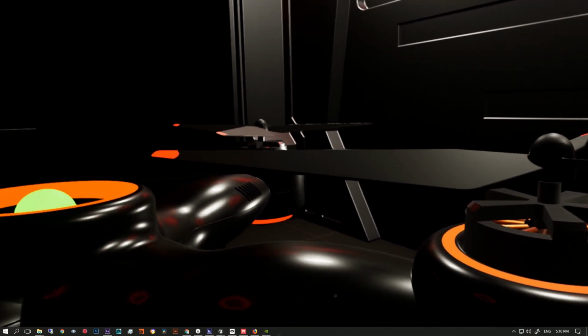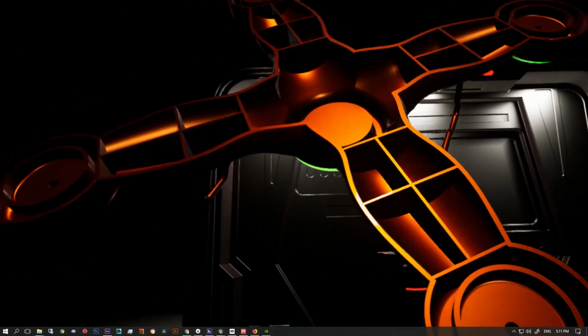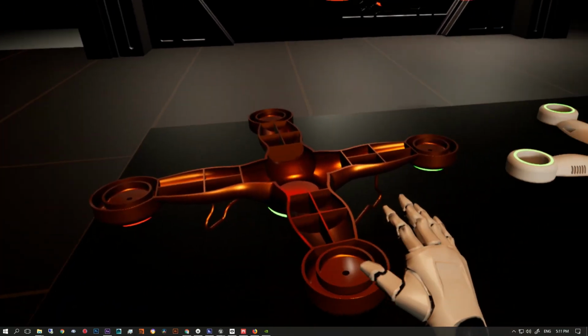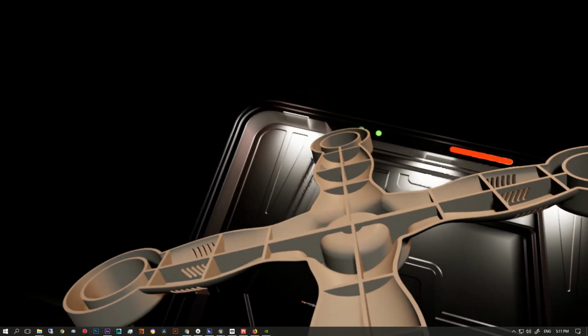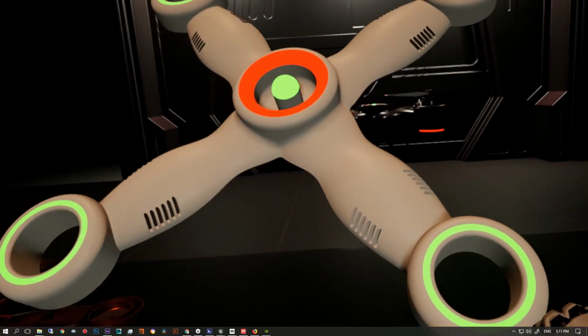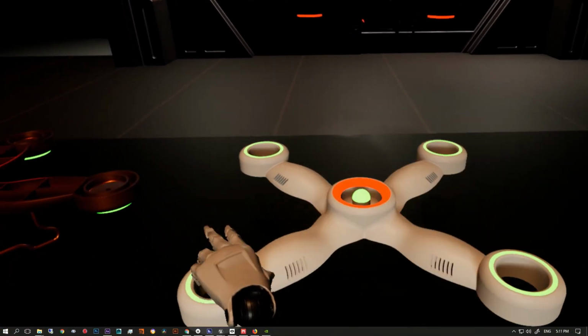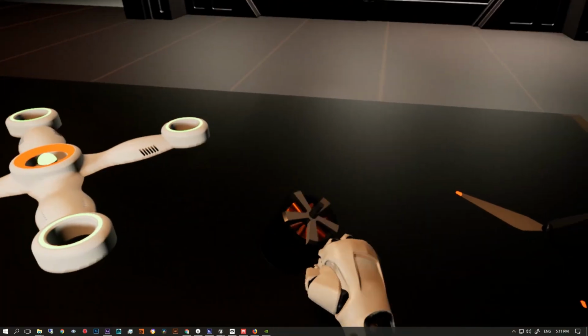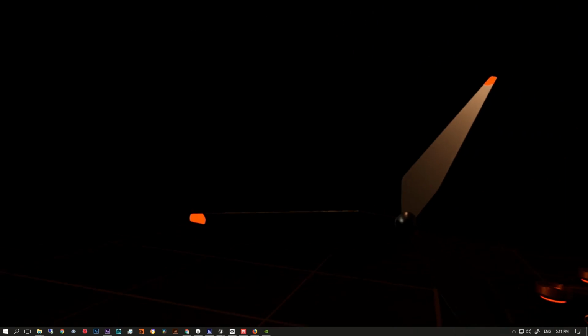Since we started working with SolidWorks, we've been trying different ways of pipelining the geometry out of SolidWorks and into our 3D package of choice, which is Autodesk Maya. When we imported directly into Maya, our meshes were pretty dirty. So now we found ourselves not just using the Datasmith plugin for real-time in Unreal, but we're also using it for imports into the pre-rendered side and the Maya side.